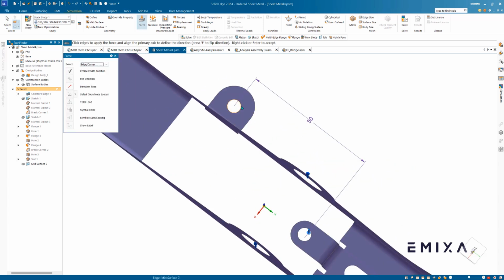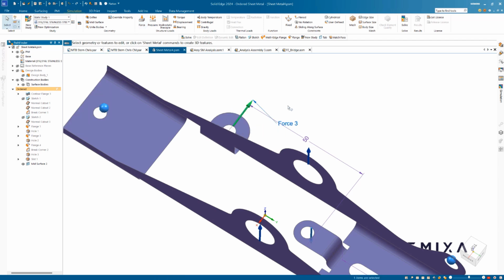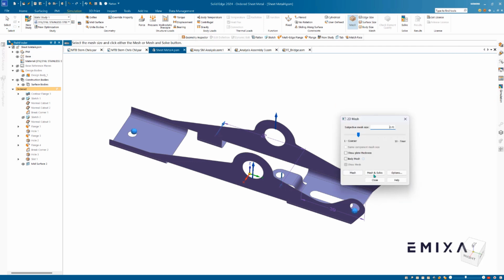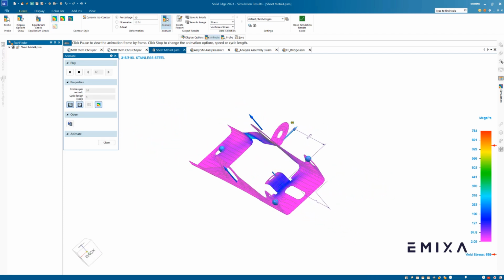on here. And this is the one that's troubling me. This little tab on here. We've got quite a load on here, and we've got quite a thin section. So that's the bit I'm worried about. Over on the right, we can see how we've got our thickness, our geometry, our constraints. And if we choose mesh and solve, it's going to take literally 1 to 2 seconds.